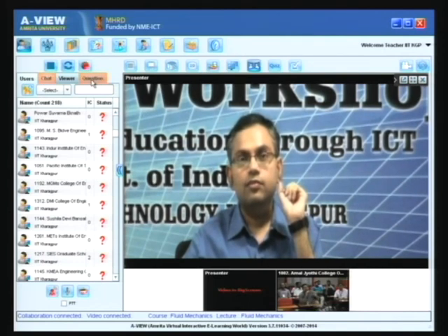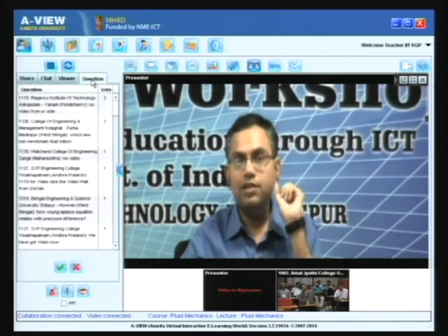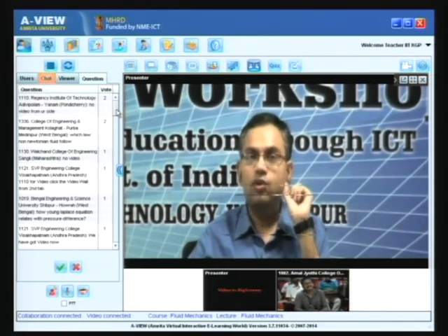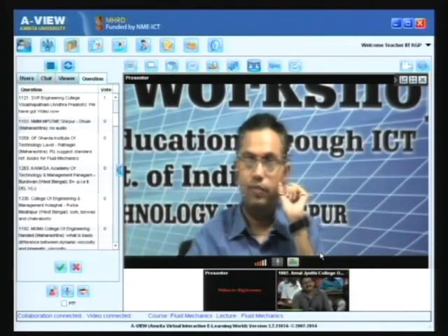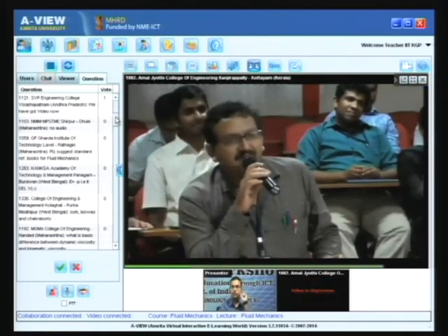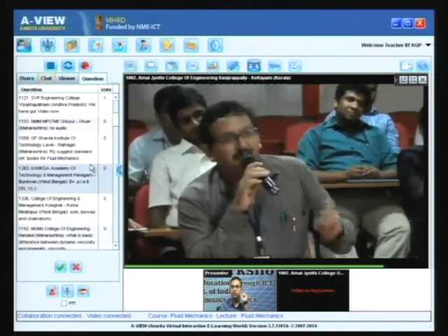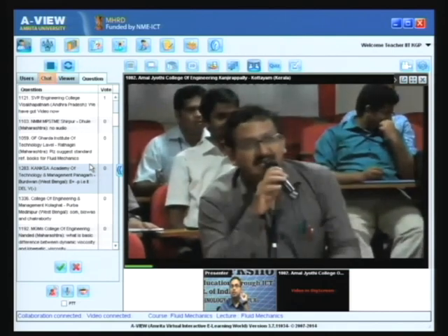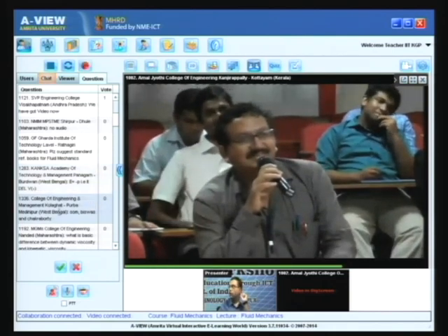Hello, good evening, sir. My basic question is whether surface tension is there in moving water. Surface tension is an interfacial phenomenon, so it is very much there in moving water. One more question: is there any limitation on the diameter of the tube for capillary action? We derived that the capillary rise is inversely proportional to the radius.